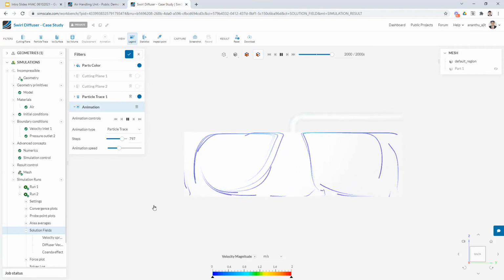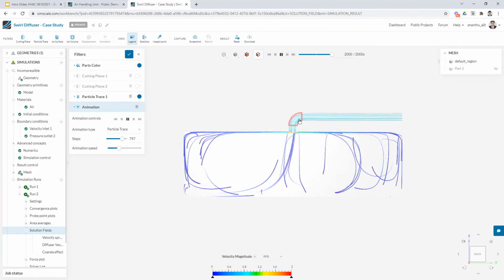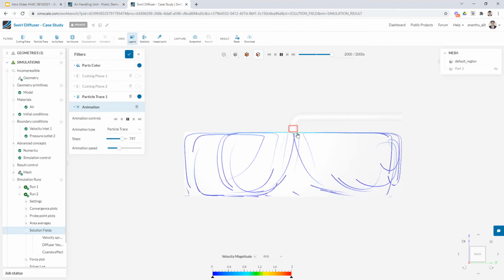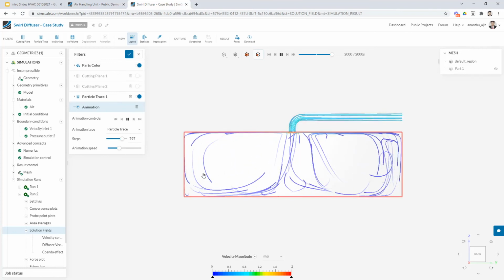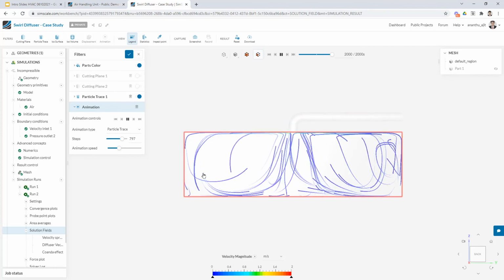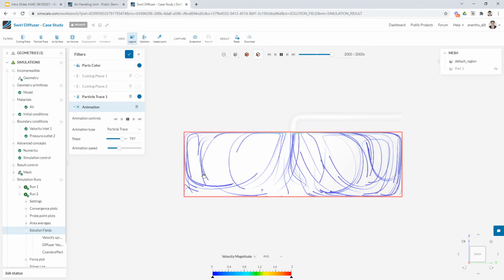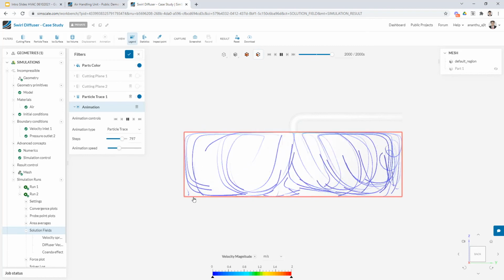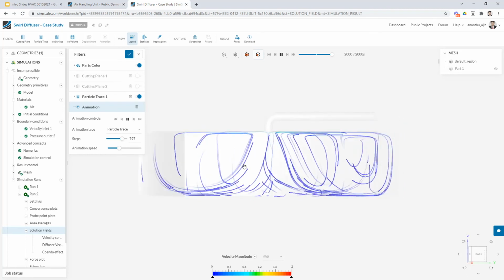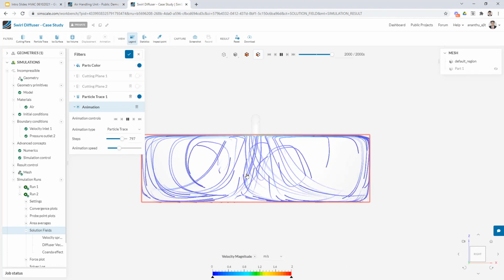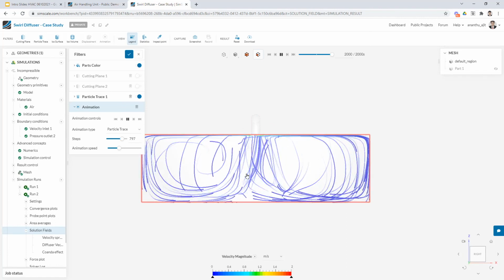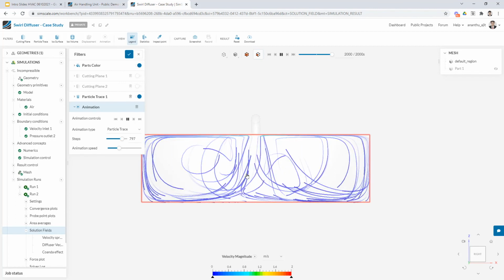Now we can already see how the air comes in from the HVAC inlet, goes through the swirl diffuser, and then spreads through the room. This way you can find out whether the diffuser is performing well, whether the air is actually moving across all the corners of the room, or if there is a dead zone at a particular part of the room which needs to be addressed for getting fresh air all through the room.